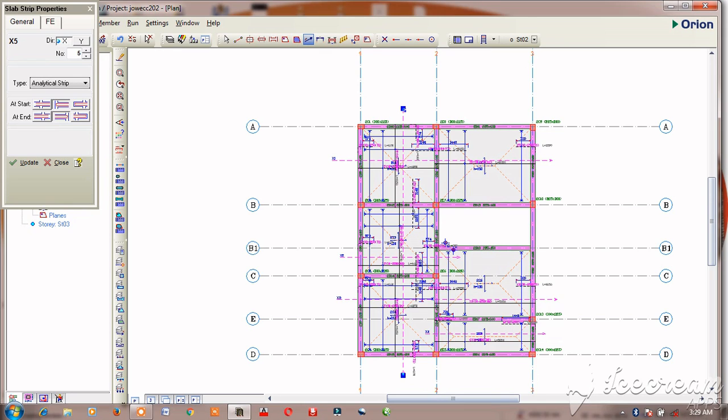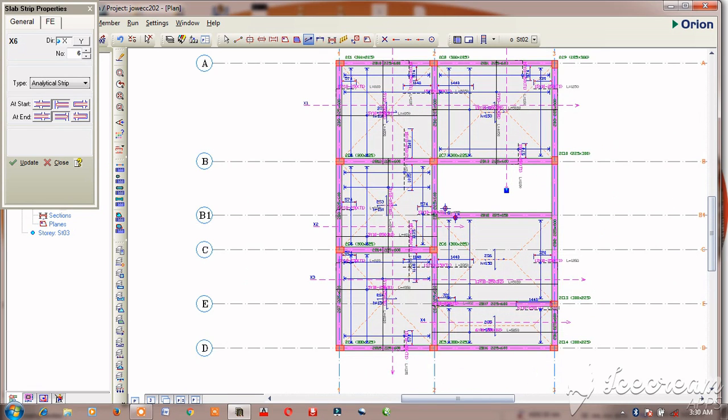So I first of all designed for the x-axis, so now I have designed for the y-axis as well. For this one as well it is discontinuous here, and also discontinuous here. So I will click here, then hold your control key, then click here. So it is now done. So this one also is sufficient. So this one as well. So click it here, then hold your control key, then